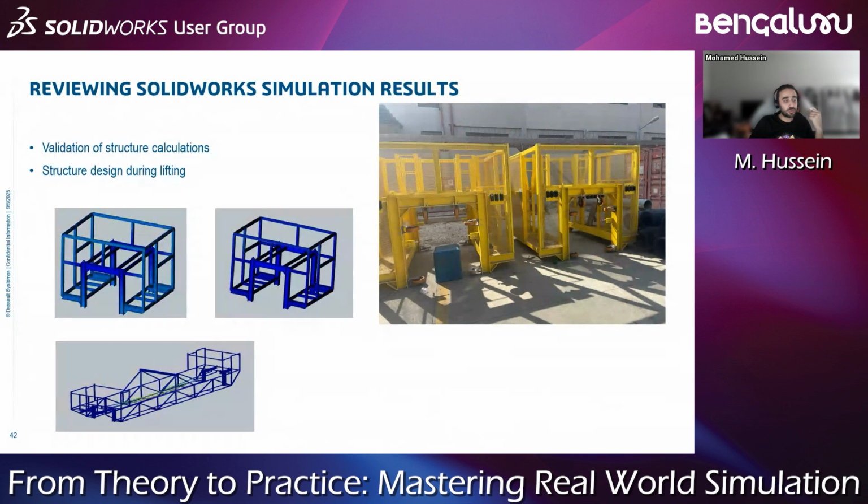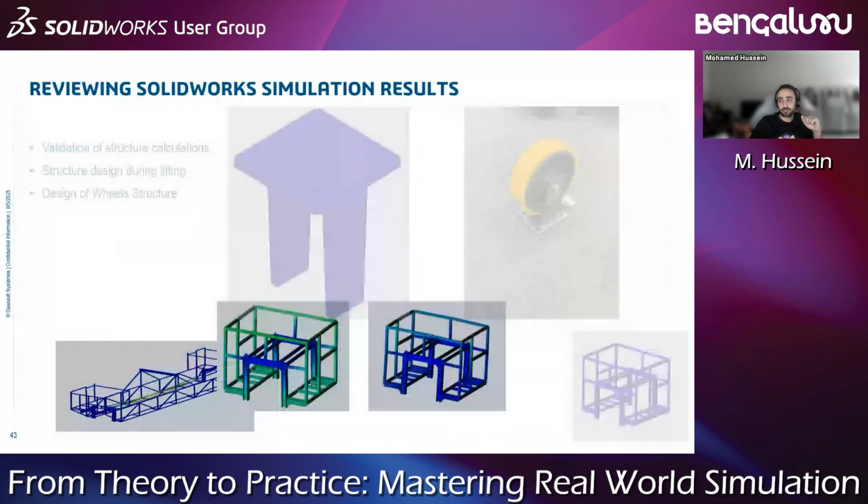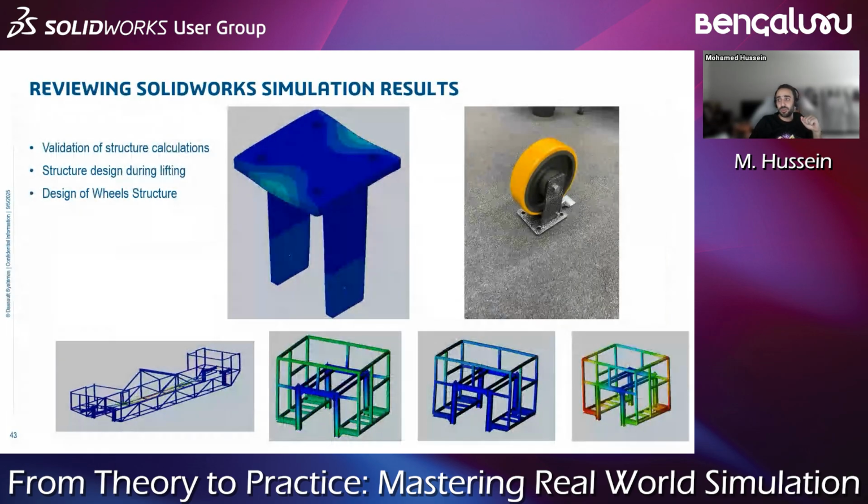Sometimes we need to add some stiffeners, which are temporary stiffeners only during lifting. Okay, only during lifting. So we need to design the wheels. First of all, we need to size the maximum reactions that each wheel will see, and we need to design this structure. We need to make sure that this structure will withstand